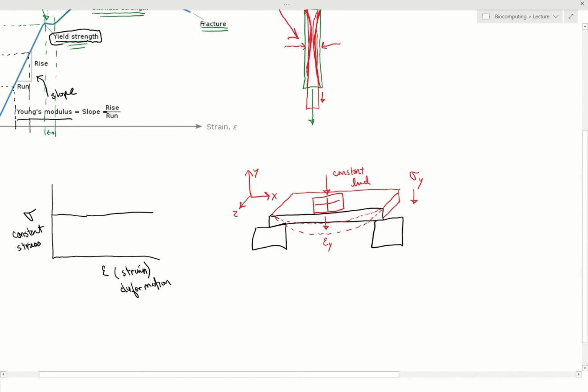In fact, it's starting to cause moments on both sides of the bridge. You're starting to get torsion or maybe even some twisting. And so if you only take into account the load in one axis, you will be doing it wrong. And in fact, the bridge may fail in another axis before it fails in the y-axis. Okay, it may fail in a different axis.